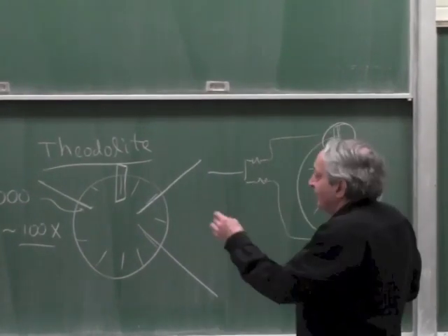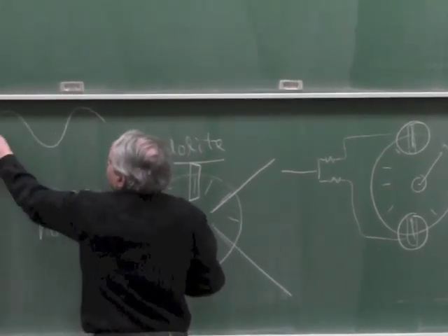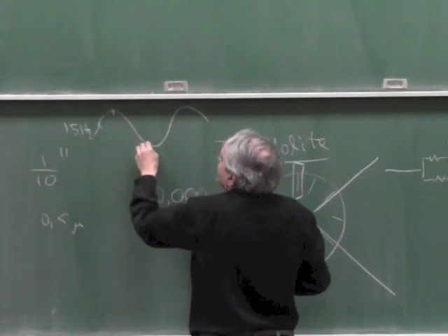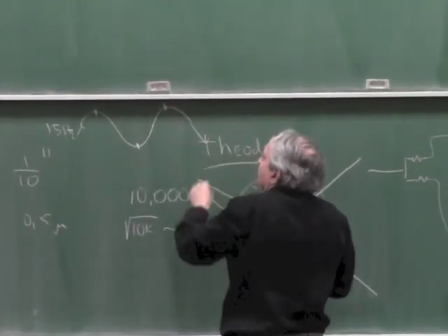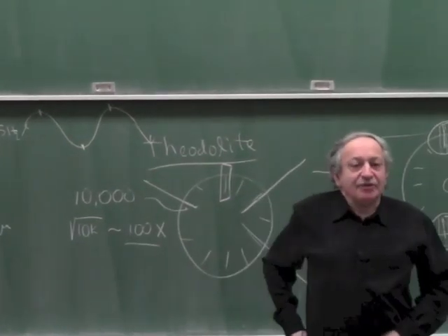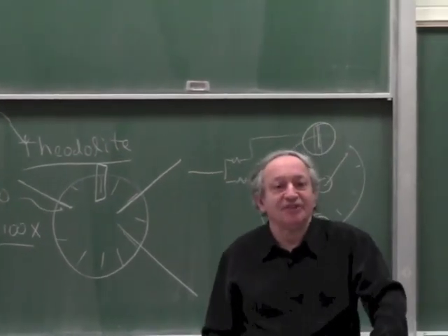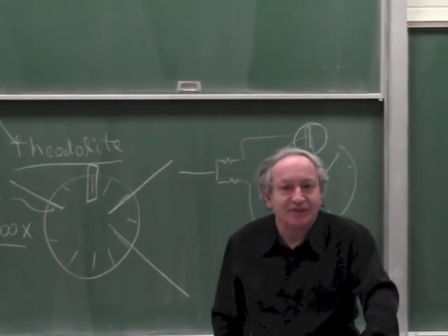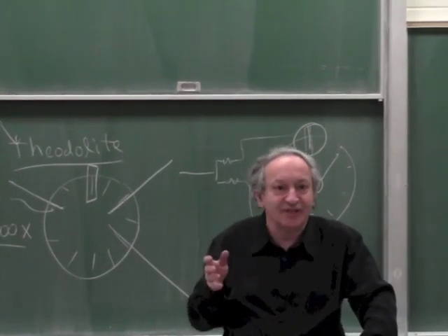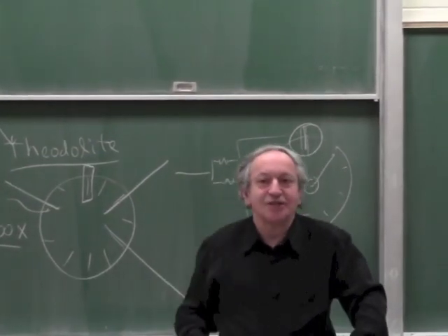Because if you have a sine wave, we went through that already several times, and that sine wave is 15 hertz, you have to sample it at least twice per cycle to recover it. That's what's called sampling theory. And therefore, a camera which is 30 hertz, its bandwidth is only 15 hertz, and 15 hertz is very bad because there's lots of things in the room which change at the rate of 15 hertz. Anybody moving, shadows, projectors, light changes.